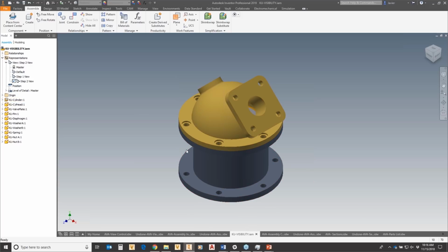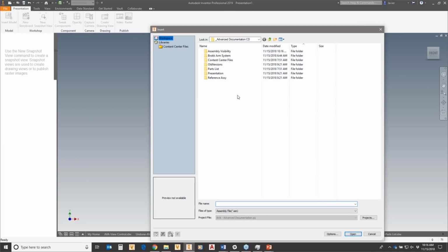So it's interesting. We're talking about documentation, but it really starts with the parts and assemblies that you work with. So new file, right? And we'll start with an IPN here. Okay. And as soon as I do this on this presentation file that's meant to take these existing assemblies apart, it's prompting me to select an assembly. So I'm going to go right here where this file exists. This is the one I was just working on.